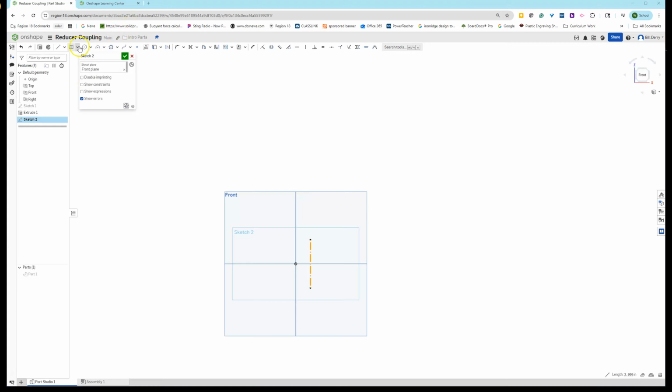I'm going to start by drawing a construction line from my origin out some distance here, making sure that it's level. And then I'm going to draw these two parallel lines. So I'm going to grab the line command, come out here, draw a vertical line, another line that is parallel to this one. Notice I'm getting that parallel, and I'm getting inference here, so I'm going to go right over that guy, connect that.